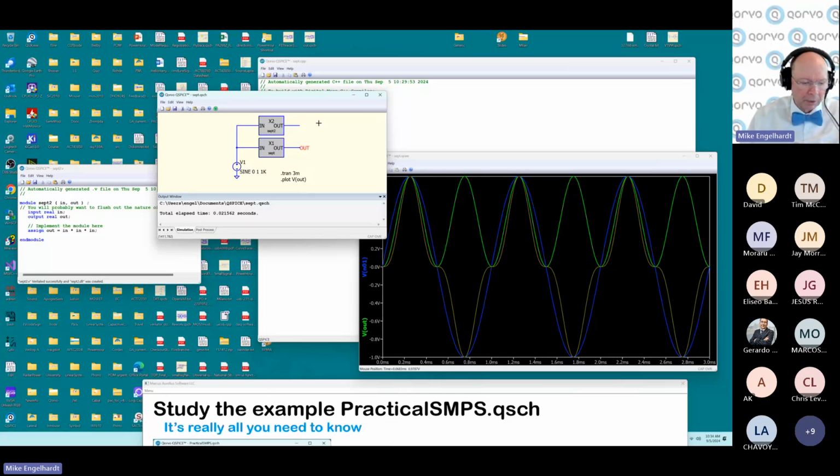It just assumes that it's a bunch of logic which is clocked, and you've stayed within the spec of the PDK of that Verilog. You don't clock it faster than it's supposed to. So all it has to do is evaluate logic. If you're writing in C, you get to know what time it is, so you can actually run things that run on time. You can generate oscillations inside your C code that the SPICE program doesn't know anything about, doesn't have to compute those time steps.